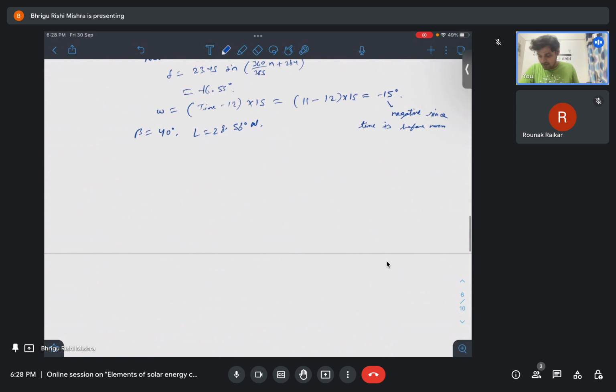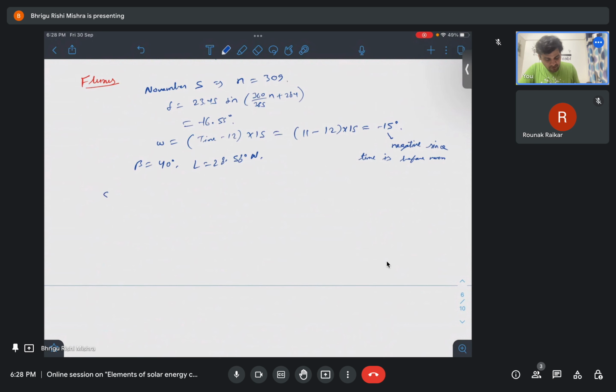So if you know the useful formula for the useful radiation, S is equal to I_B/R_B plus I_T by C, times tau rho_E alpha. Okay, so this is the formula. We have already been given tau alpha. What is rho_E? Rho_E is the effective reflectivity of the concentrator.